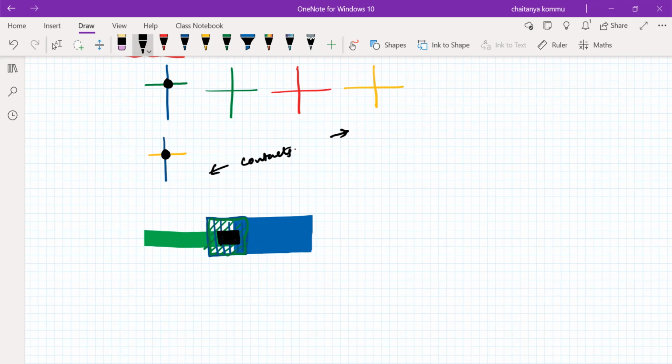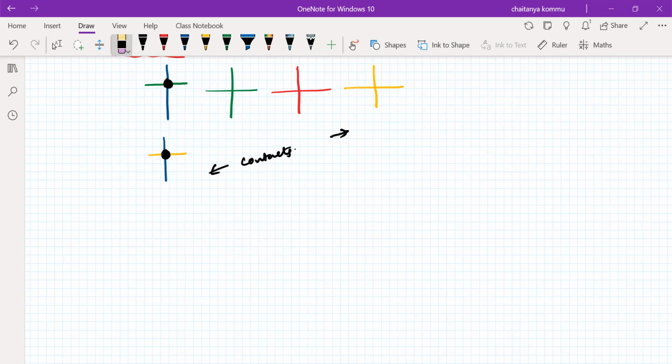So therefore, what is the overlap region dimension here? It is actually 4 lambda. What is the dimensions? Okay, I think it's not the right way. Better I will do it once again. What is the minimum dimension of the N diffusion? 2 lambda. What is the minimum width of the metal? 3 lambda. Now what I'm going to do here is take the overlap region of 4 lambda by 4 lambda.